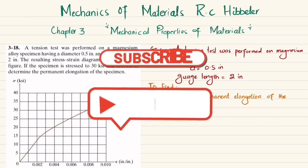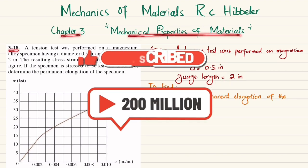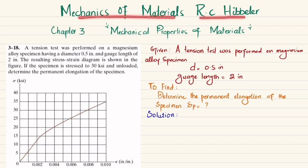Welcome back. In this video, we are going to solve problem 3-18 that is taken from chapter number 3, Mechanical Properties of Materials. The book name is Mechanics of Materials by R.C. Hibbeler. The statement is: a tension test was performed on a magnesium alloy specimen having 0.5 inch diameter and gauge length of 2 inch. The resulting stress strain diagram is shown in the figure. If the specimen is stressed to 30 KSI and unloaded, determine the permanent elongation in the specimen. So you can see this is the stress strain diagram for the magnesium alloy, and we have to find the permanent elongation if it is stressed to 30 KSI and then unloaded.